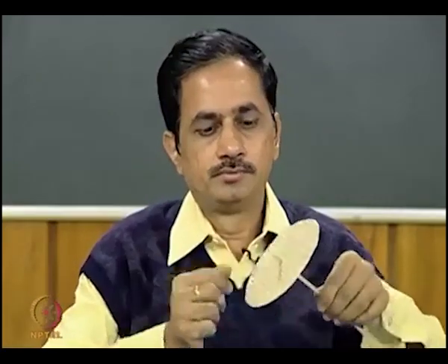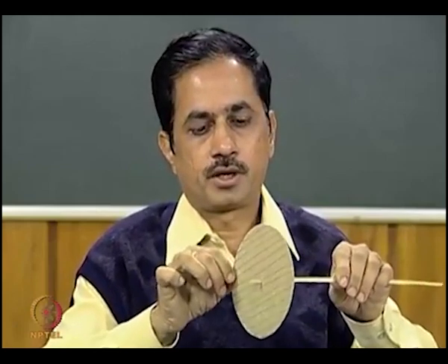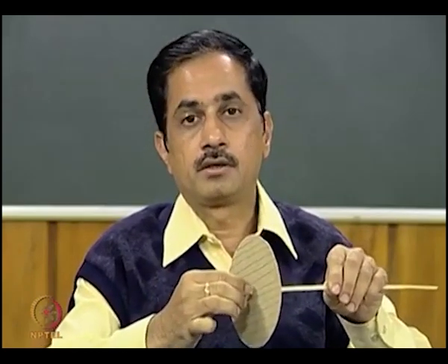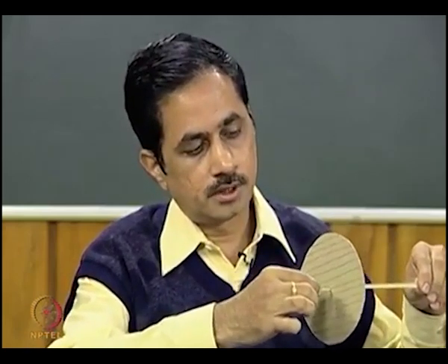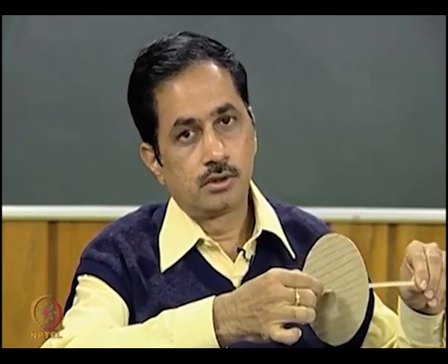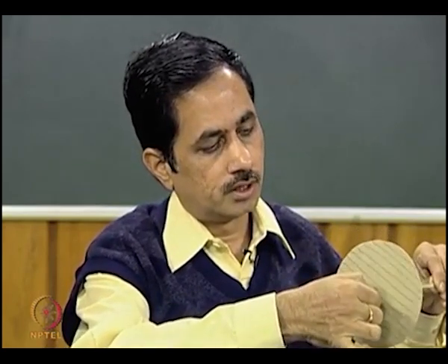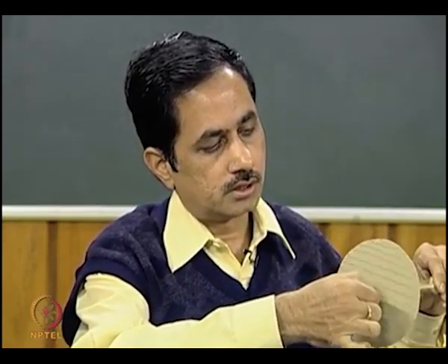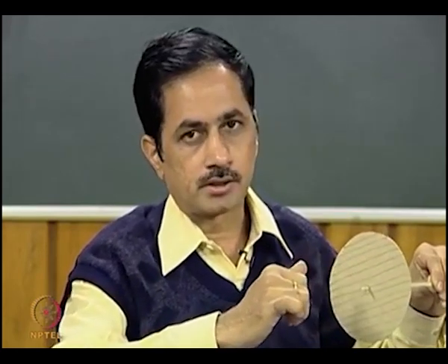So now let us see what torsional oscillation is with a simple model. In this particular case, there is a thin shaft and a relatively rigid disc, and torsional oscillation is nothing but if we give a twist to this and leave it to oscillate. You can see that if I give a small twist, this disc oscillates about its mean position, about its own axis.